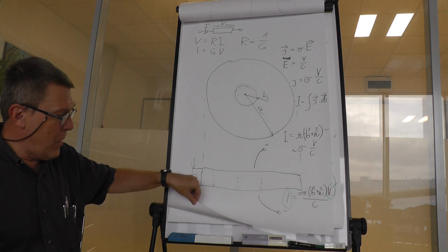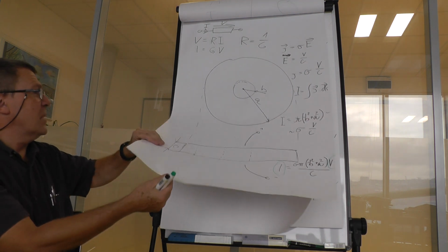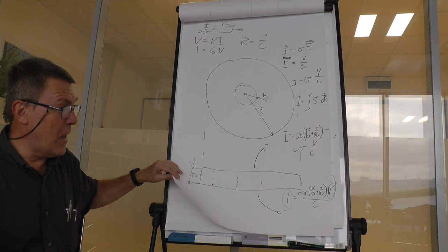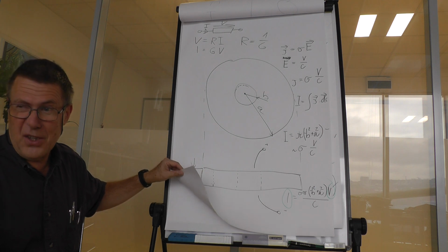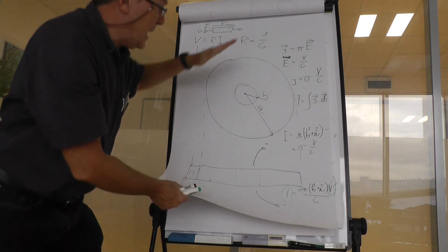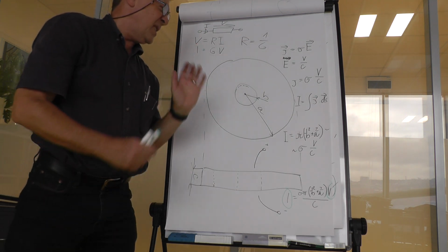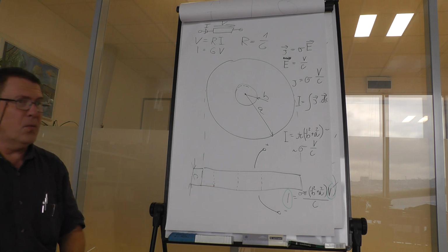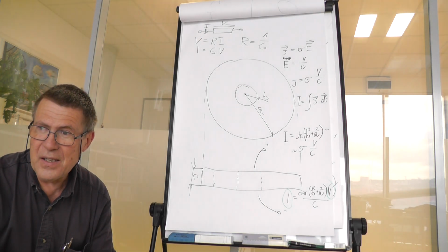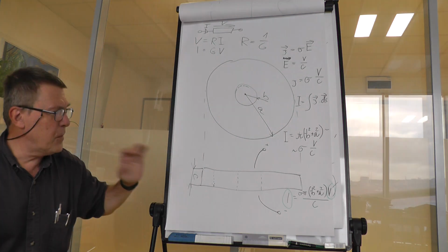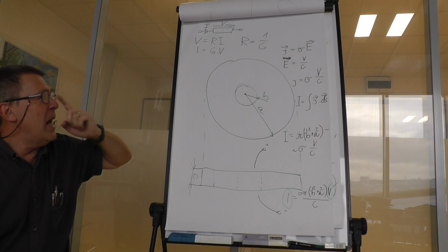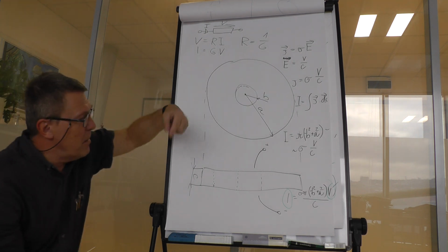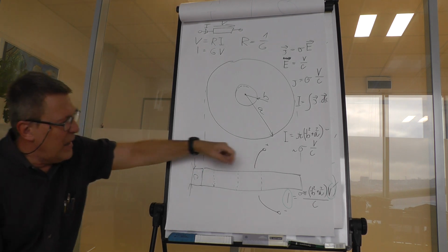Now I will use a different way for the same geometry where the current field would not be homogeneous, and therefore we would have to use another kind of computation, a real integral computation. So let's take the same surface, just we would immerse that resistor into, for example, strong acid and get away all the metal out of it. So we will be left only with a carbon disc with a hole inside. And now we shall again deposit conductor on it, but not on those two surfaces, but only inside the hole and on the outside of the disc.